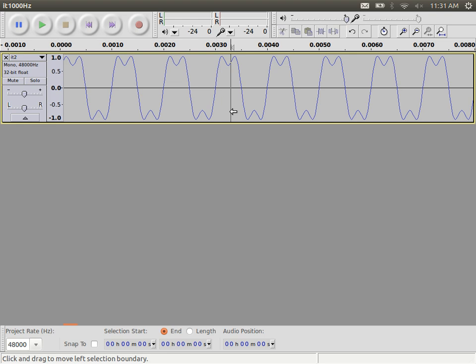What's the bandwidth? 4,000. The bandwidth is very easy to see from this plot. Just look at the highest component and the lowest and take the difference. It's the width of the frequency band. 6,000 minus 2,000, we get a bandwidth of our signal B of 4,000 hertz.